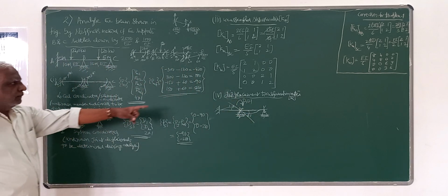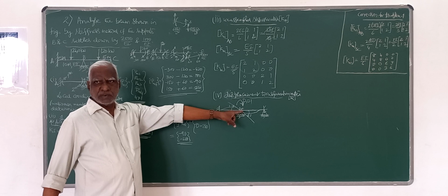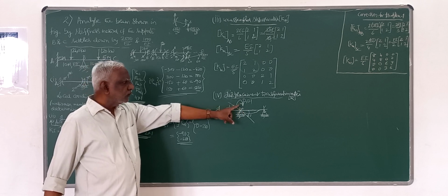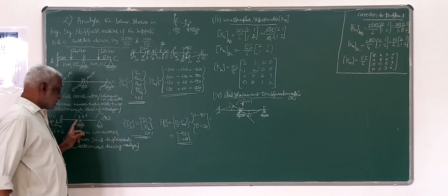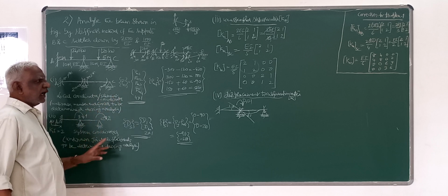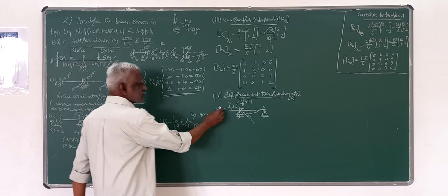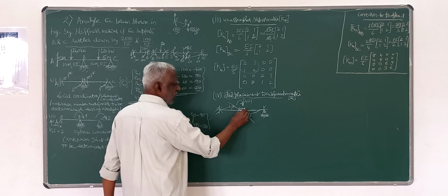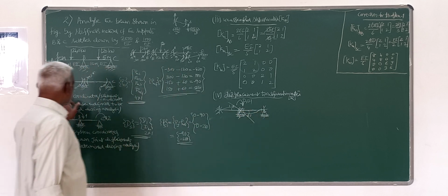As I told you, you have to give unit displacement along one system coordinate at a time and determine the displacements generated along each of the element coordinates.